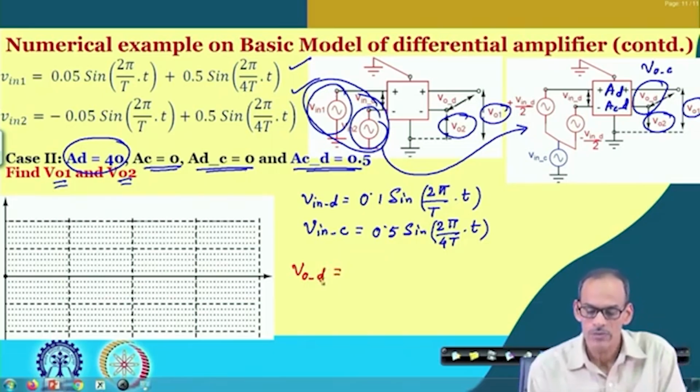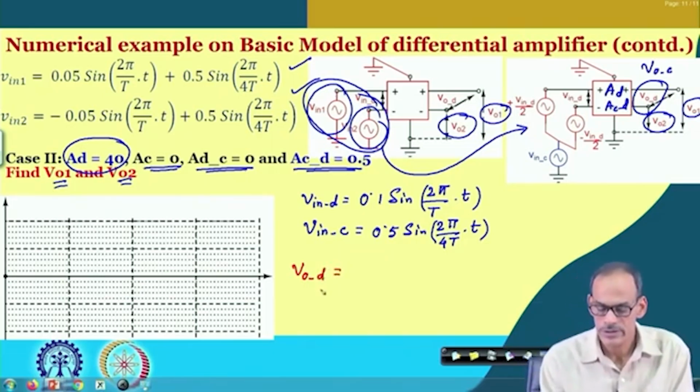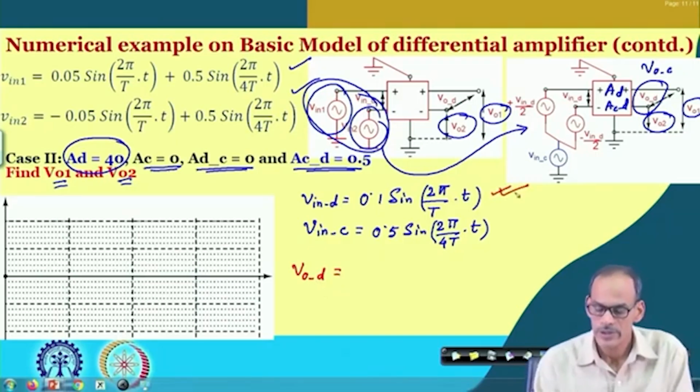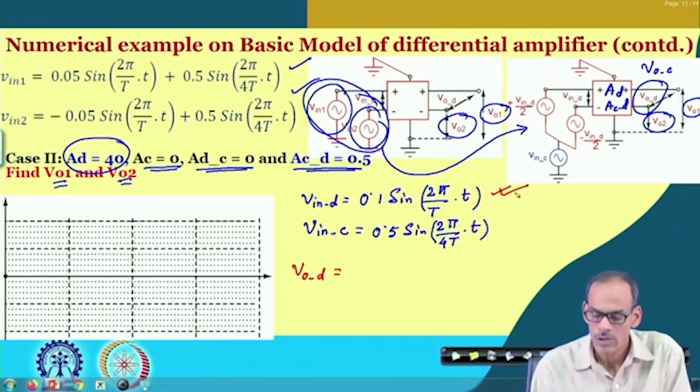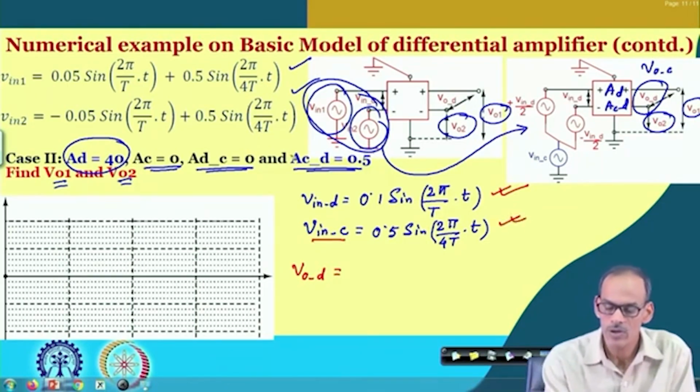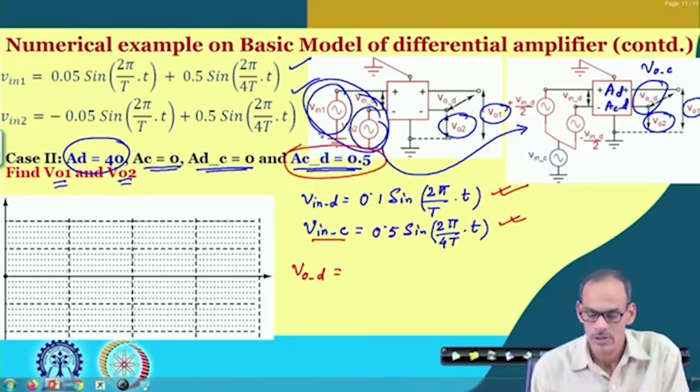First of all, VOD is a combination of the output coming from the differential input, and also this common mode signal, which is getting converted into differential form because this parameter is non-zero.